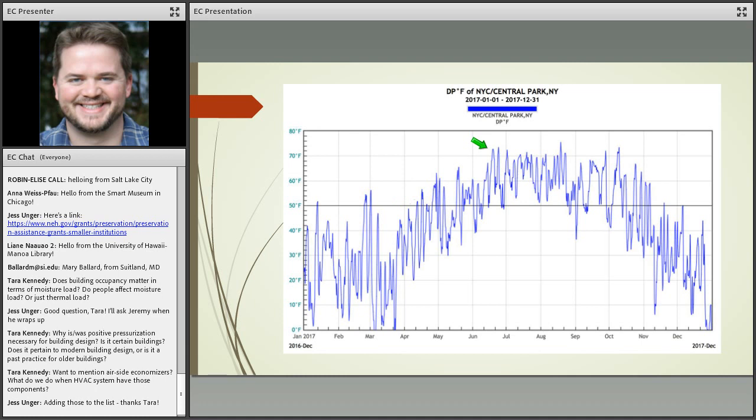And all of these days, all these hours of the year up here, where we're above a 50-degree dew point, I have to dehumidify in order to bring that moisture content down to my right interior content to maintain that flat line. So the takeaway here is that if we want to look at that flat line control indoors, that 70-degree, 50% relative humidity condition, I have to work on moisture content all year long.